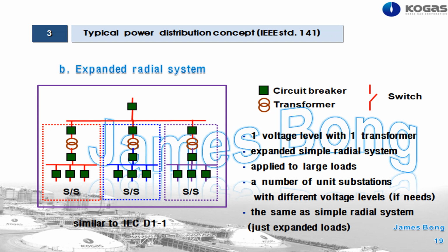This is efficient in a small industrial plant. The plant which has this distribution system cannot avoid the electric power shutdown when it needs repairing or maintenance of the incoming line. At the unit substation, if necessary, repairing is possible without the whole unit substation's shutdown.